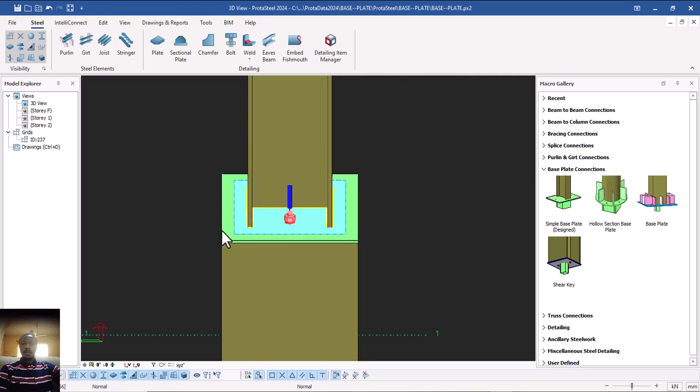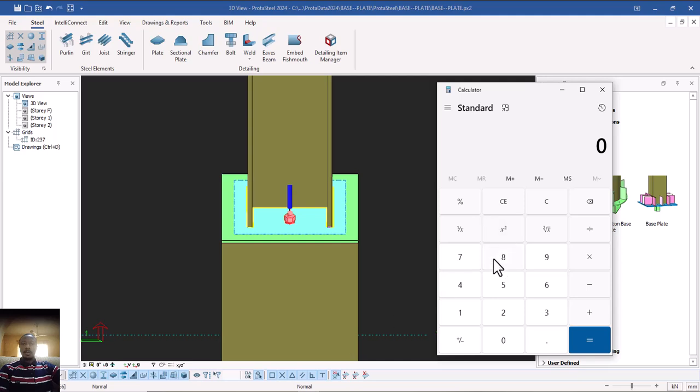We want a small distance at this edge, because if your anchor bolt is too close to the edge, it can cause a crack. In fact, if care is not taken, if the load is much, it can even pull out. So we need a reasonable distance. Therefore, how do you calculate your distance? You pick your calculator. Don't forget we are using diameter 20 for our anchor bolt.